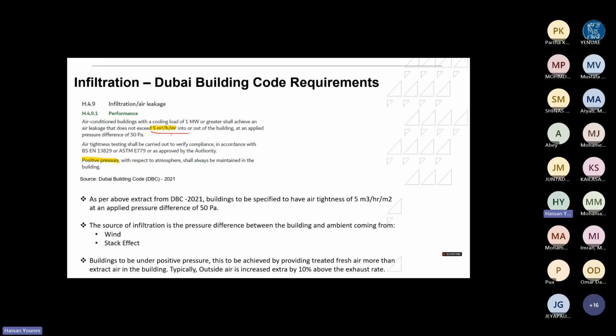That's more computation time. Some people will say, oh, let's just assume 0.2 air change per hour. That does seem sane. Let's do that and cut to the chase and figure out what the consumption due to the infiltration is. You can do that. But again, figure out what you're trying to achieve in your building, and the choice is yours.